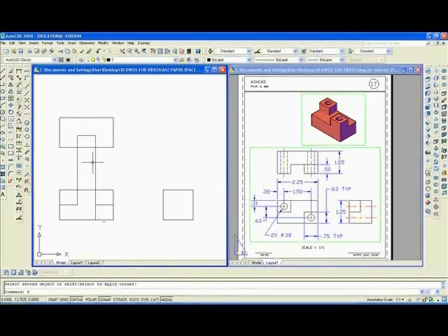break, BR, enter, F for the first point, second point, didn't work, try it again, BR, enter, break this line, F, enter, the first, that point. That point. And we can fillet it with radius 0.